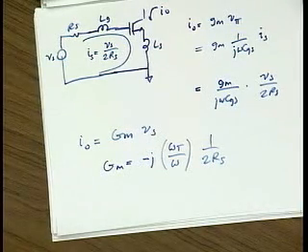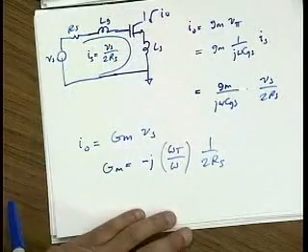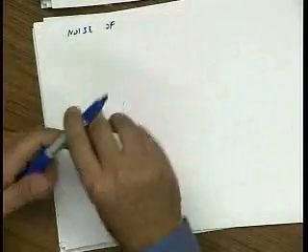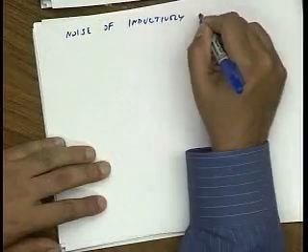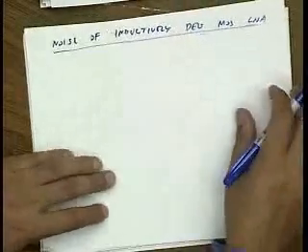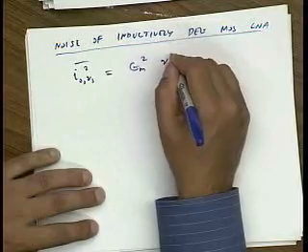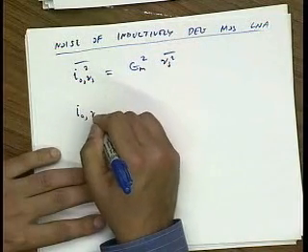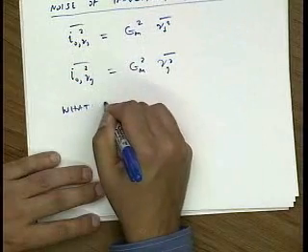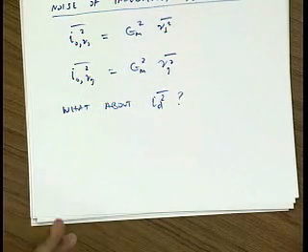Okay. Now this is useful because now any input noise voltages in this loop get output referred by GM squared. So if I do a noise calculation, let's start to look at the noise of the inductively degenerated MOS LNA. I can say that the output noise due to Vs is simply GM squared times Vs squared. And the output noise due to V gate is also the same thing, GM squared times V gate squared. So the question is, what about I drain? Remember before, I drain just simply flowed into the output.